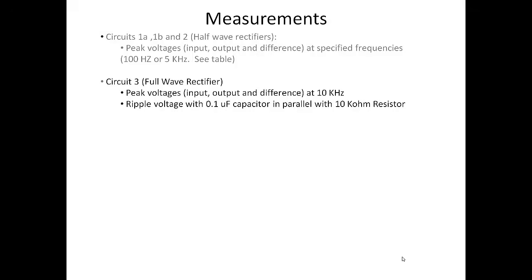output. To do this, it may be easiest to change the coupling on channel 2 of the oscilloscope from DC to AC. This blocks DC voltage at the oscilloscope input and forces the signal to be symmetric about 0 volts. I will review how to do this in the video portion of the lab. But don't hesitate to ask the lab monitors for assistance if you have trouble setting the coupling to AC. Be sure to change the coupling back to DC when you're finished with this measurement.